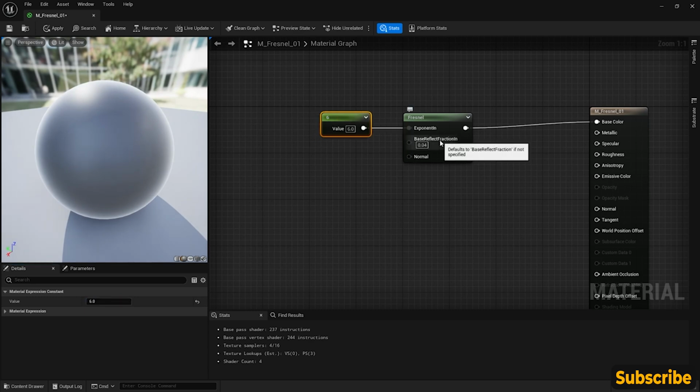Now, the base reflection fraction, we can basically leave this as default or the normal. So if we have a normal map or other information, we can feed that in to help affect this, because again, this is looking at the reflection of the angle. So if we have these little normals, we want to take that in to make it look a little bit more real.